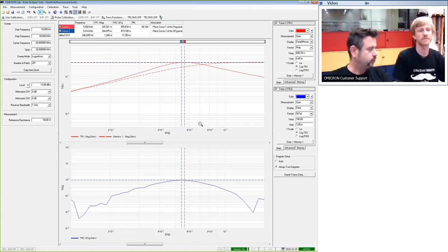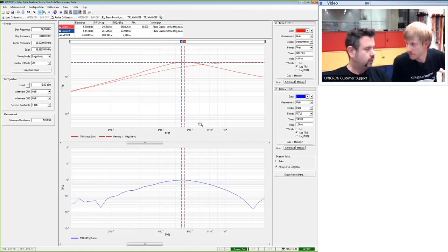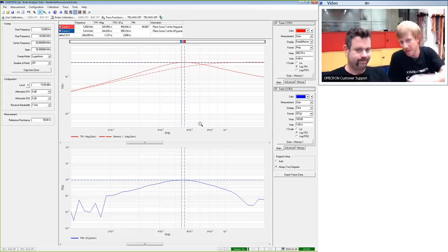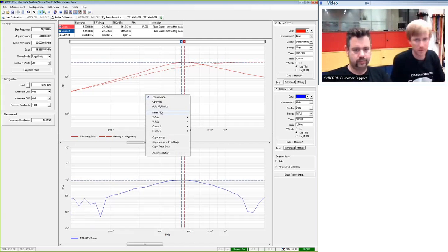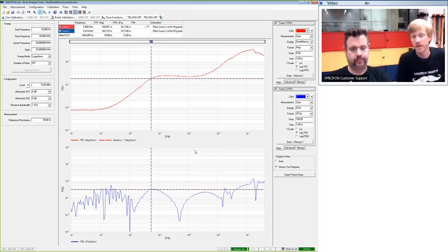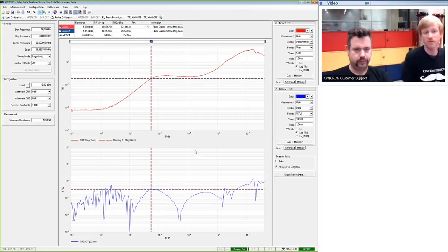Yeah. So if you just activate the electrolytic capacitor, then we can show that it becomes a little bit more tricky to find the correct position of the peaks. There are no peaks, in fact, anymore. Can you maybe reset the axis such that we see the picture? And I will now switch off the tantalum capacitor such that only the aluminum capacitor is switched on. And immediately we can see that the curve doesn't show a peaking anymore.